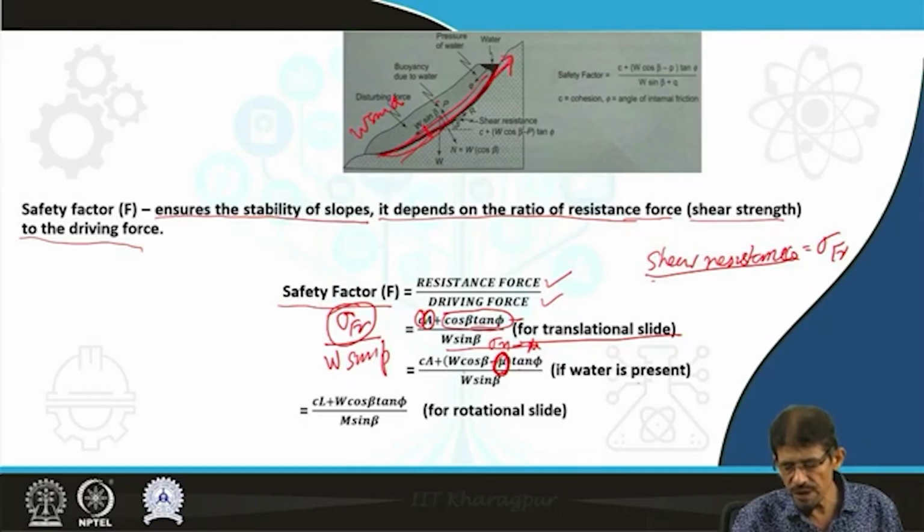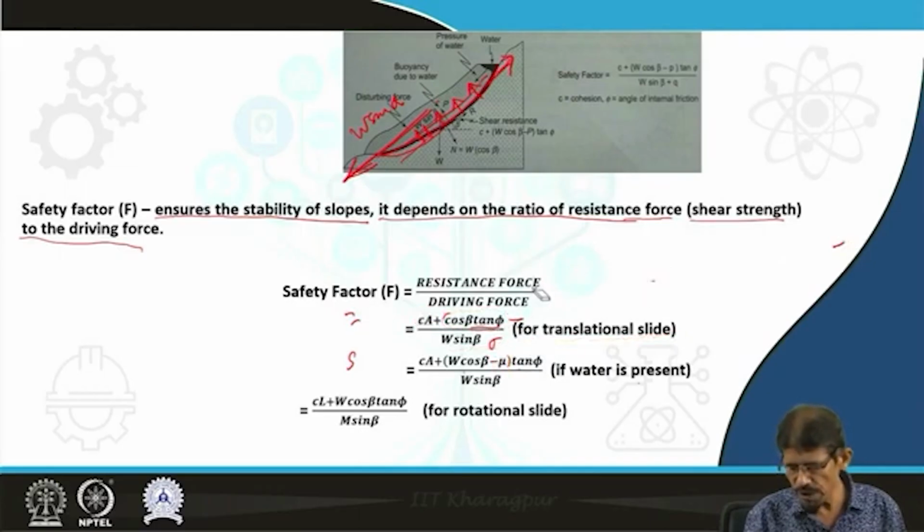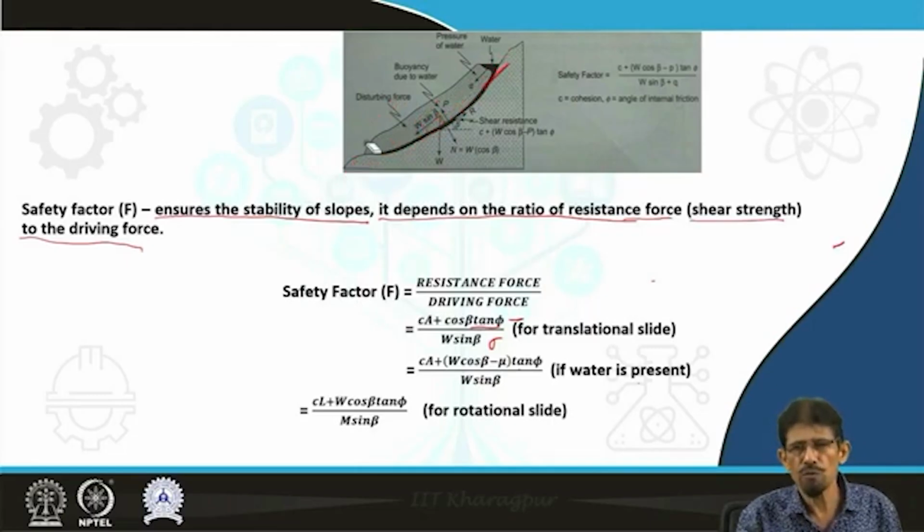If frictional resistance is less, and there is an upward acting force due to water, in such a situation the downward dragging force becomes more effective, and in saturated condition this mass is going to slide. Friends, in rainy seasons we observe a number of slides due to saturation of slopes. Therefore, mountain people are more conscious about the rainy season, because saturated slopes are more prone to slides due to reduced frictional resistance,